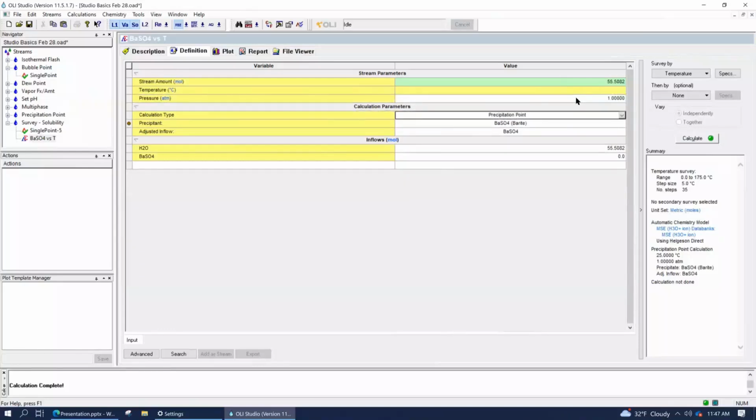At 1 atmosphere, what that means is, if I go above the bubble point, if I change the temperature of this water so that the vapor pressure of water exceeds that confining pressure, then I'll evaporate the system. So if I'm going to do a calculation at 175 degrees Celsius, I need to make sure that I have a confining pressure that'll force the liquid to remain a liquid so it doesn't evaporate.